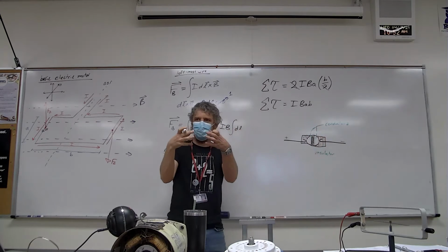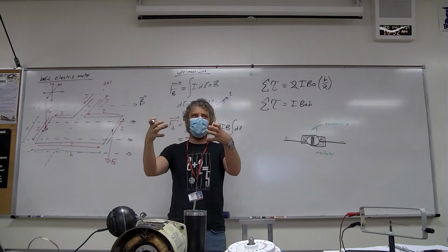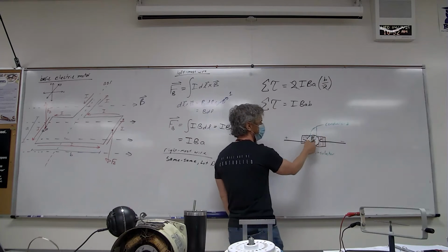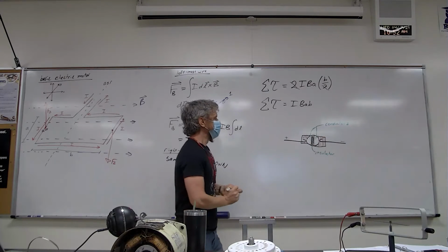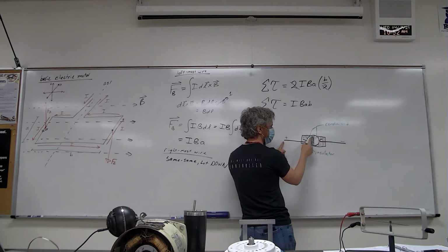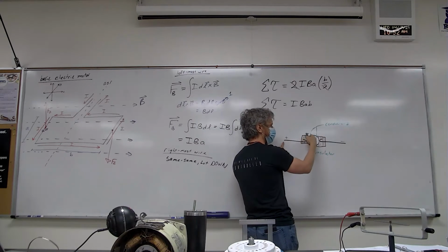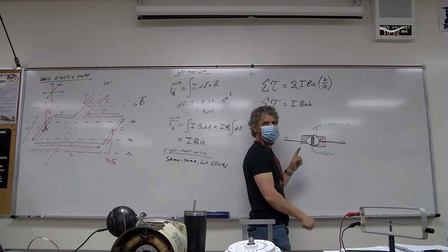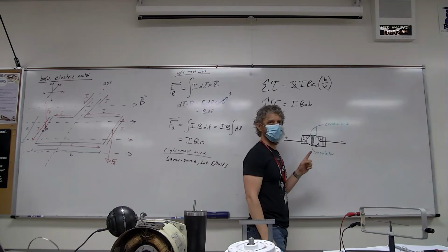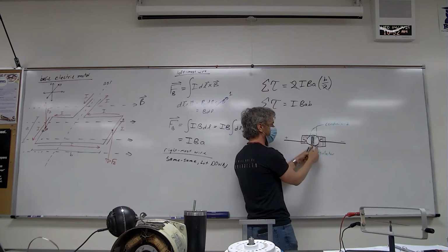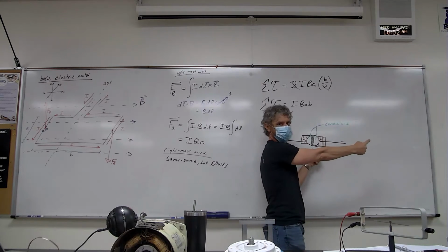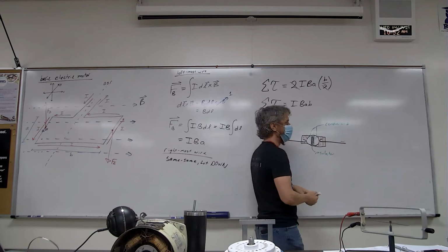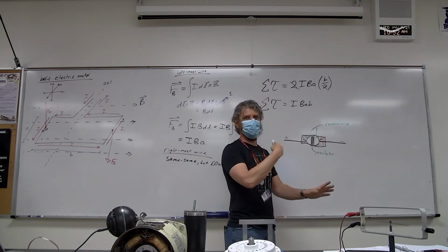If you notice, the thimble had 3 sections, 2 outer sections and 1 inner section. The outer sections are metal, conductors. So this brush touches this metal and puts current down into that wire in the coil beneath it. And it goes from this coil to this coil and then up and out through this one, right? The current goes in that direction. Are you with me? Which causes rotation.